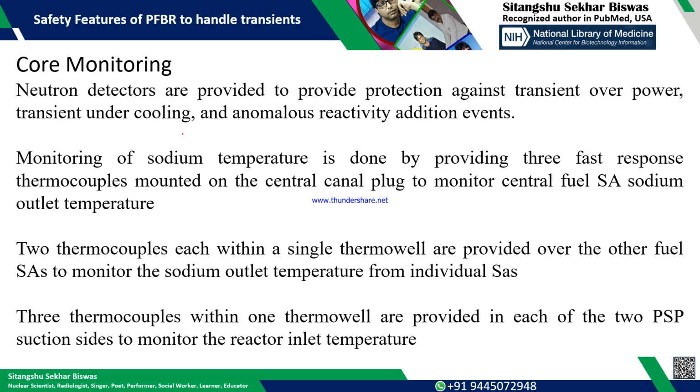There are three thermocouples; the response time is quite higher. I think it may be Thermocoax make. These are provided in each of the two primary coolant pump suction sides to monitor the reactor inlet temperature.